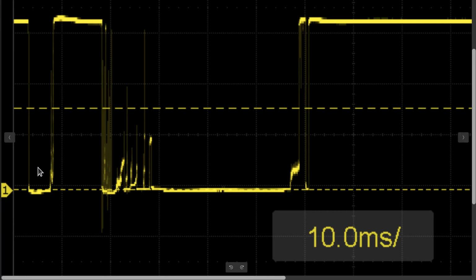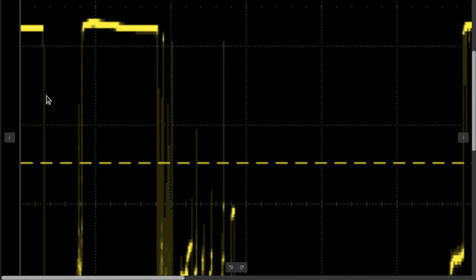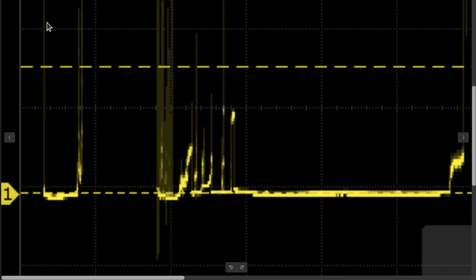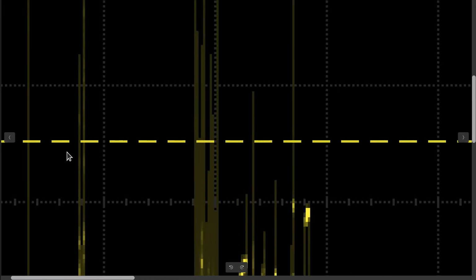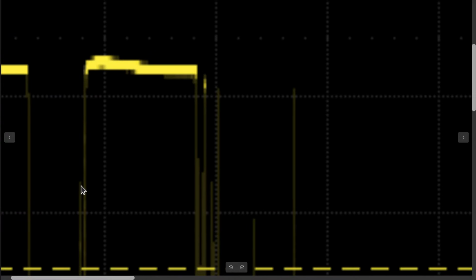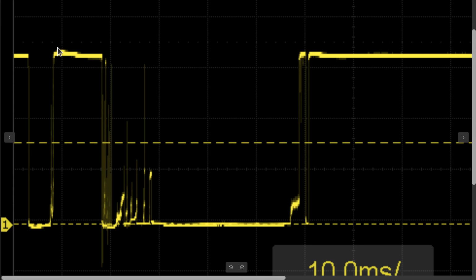So this is your problem, right? If you're sampling this quickly, you might see a 1, then you might see a 0, because this edge looks pretty clean here, at least at this far away vantage point. Who knows? It could go up and down a couple times in there. It certainly does go up and then back down and up again here. I don't know if that's high enough, but it certainly might look like a 1 followed by another 0, followed by a 1 and then a 0 and then a 1. This is a big problem.